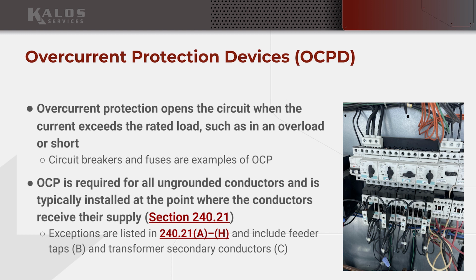And so if we've done our bonding, we've sized our bonding conductors and our grounding conductors properly, everything is connected to the proper torque ratings, everything's connected up nice and solid, and we've established a low resistance path back to the source. What's going to happen is, when we have fault currents, fault current being line 1, line 2, line 3 making contact with ground, with what we call non-current carrying metals, right? They carry current because they're metal, but when we say non-current carrying, we mean they're not supposed to carry current. We want to remove that voltage. That's why we grounded it.